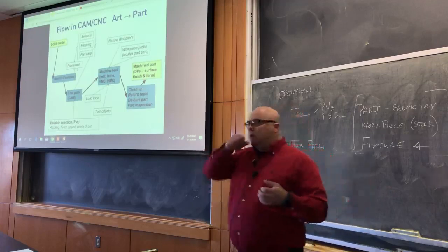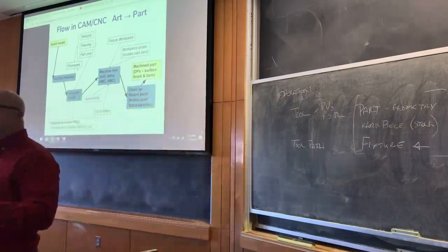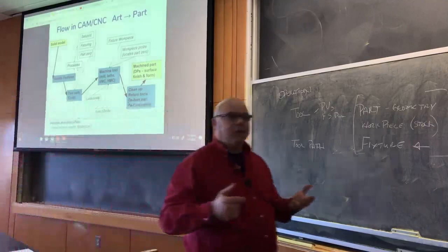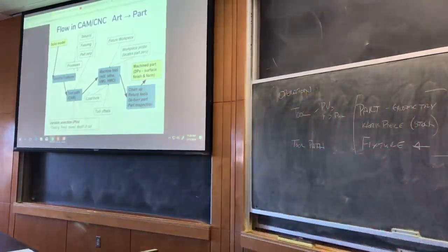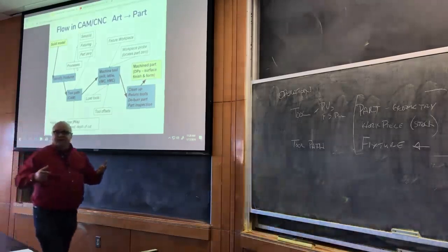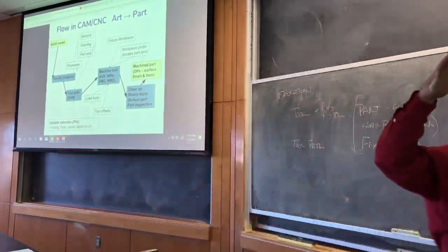When it enters and exits, there are different forces, and it's like the difference between statics and dynamics, right? If we have a steady state operation, we can have velocity, but as long as it's constant velocity, it's a statics problem, right? You guys have all had statics and dynamics, or most of you have, right? Yeah. So as long as it's constant velocity, there's no acceleration, it's statics, not dynamics. It becomes dynamics once there's acceleration.